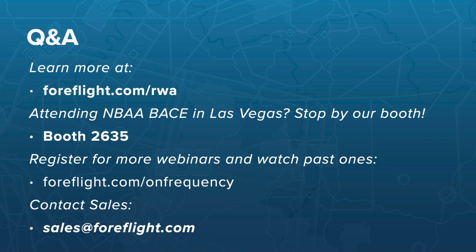However, Runway Analysis is when you've lost the one engine during takeoff, at or prior to V1, really at or after V1. And so we're not talking apples to apples here. As far as whether our solution is approved, or for that matter, any runway analysis solution is approved, I prefer to use the word accepted rather than approved, because it's technically and typically operator specific and up to the operator to show their POI that this is how we're doing our engine out operative procedures, and here's the results that it gives us, and do you have an issue with it?